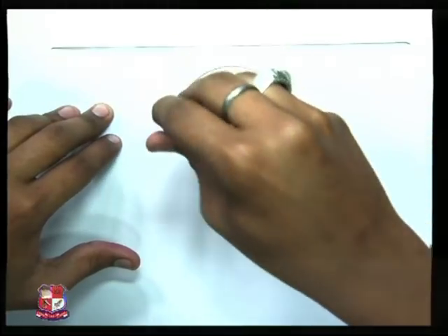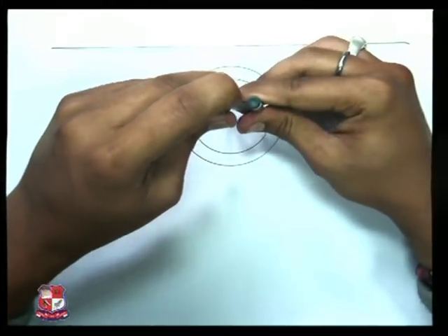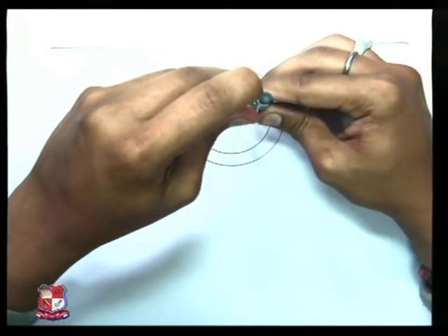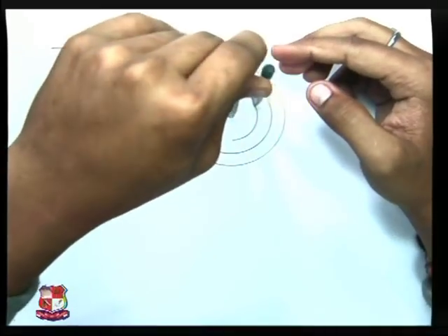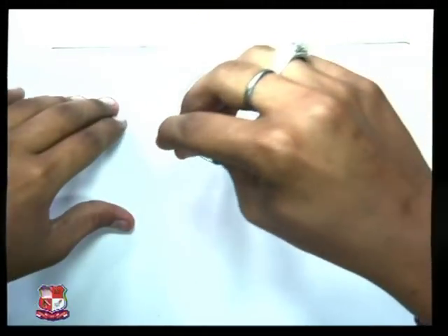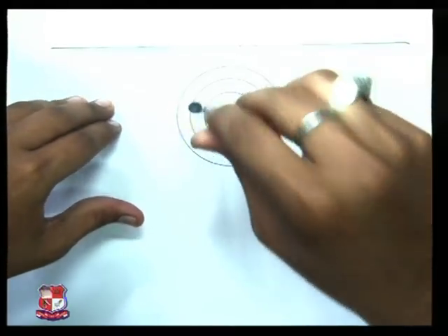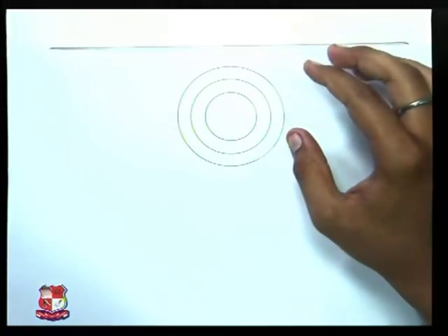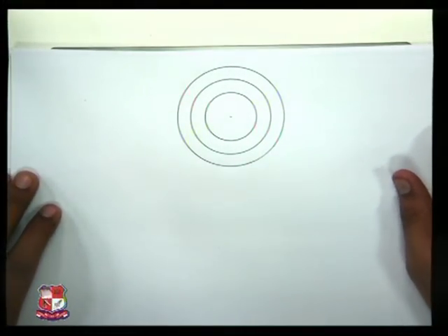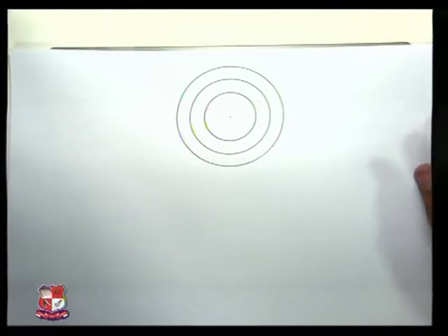This is the outer portion of a body, so that's why it is a thick line. Thick doesn't mean that it should be very thick. Thick means that it should be clearly visible compared to the dimension and projection lines.